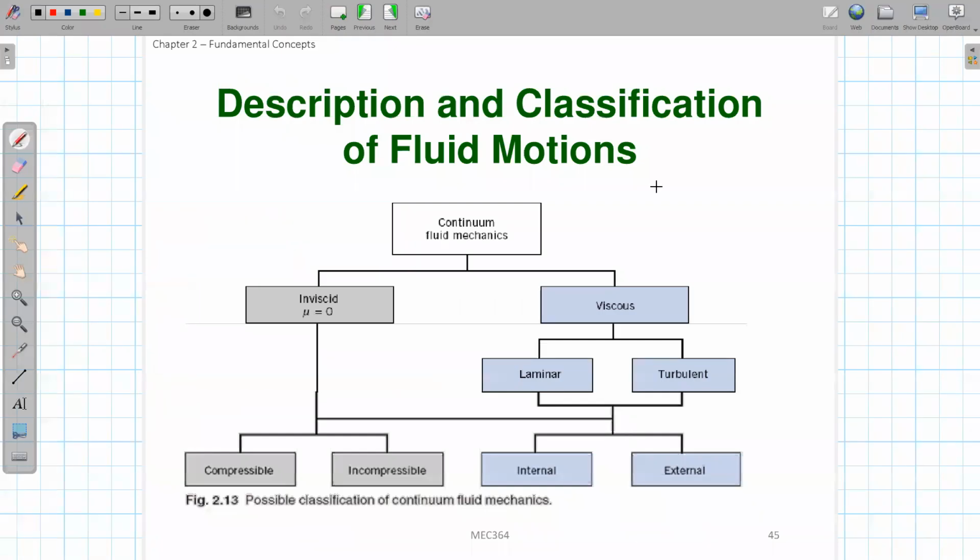It's like, if you have fluid coming from this orifice, and in the beginning I draw a line here, arbitrarily selecting particles at t equal to 1. I want to see what this line will look like at t equal to 10. Maybe it's going to look something like this. So it doesn't track any one path, but an arbitrary surface.